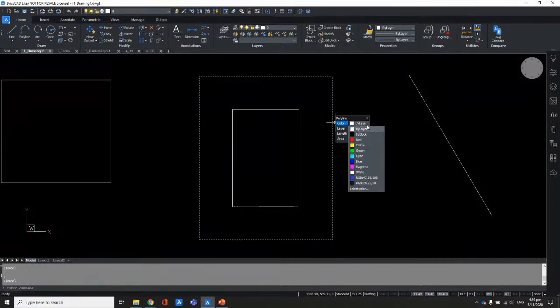So it's telling me that it's a polyline and what color it is. I can actually change it from here if I wanted to, and the layer as well. I can also change it if I have a longer list of layers. Then I can choose further, but I'll keep it there. And it gives me information on the length of this specific entity. This whole polyline means that it's 360 cm, based on the dimensioning that we did earlier, and the area is 0.8 square meters. So I think this type of information offhand and very quickly at your fingertips is very useful.